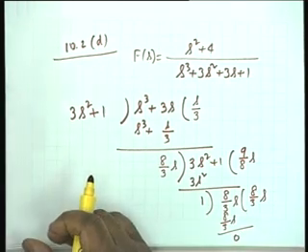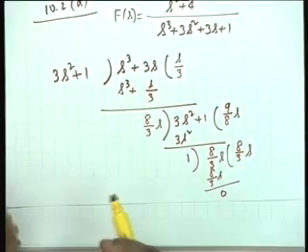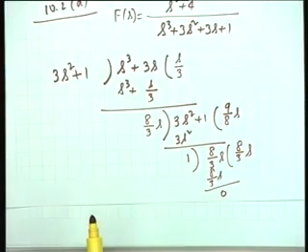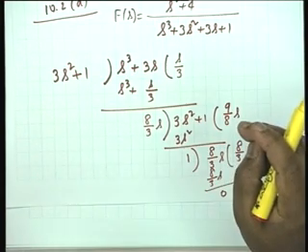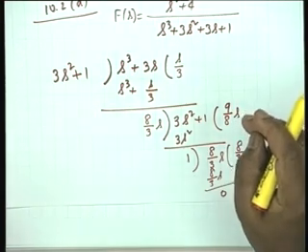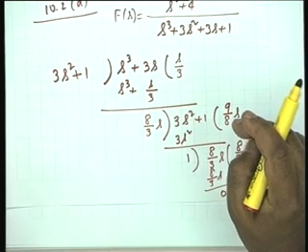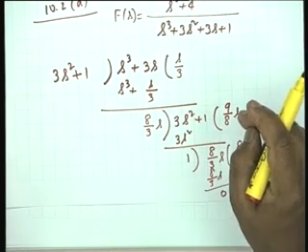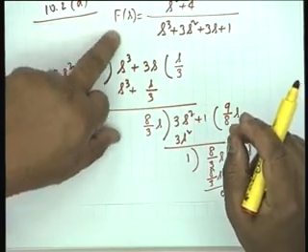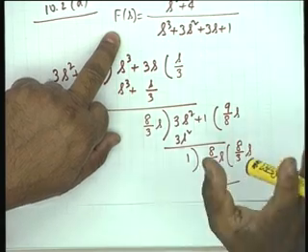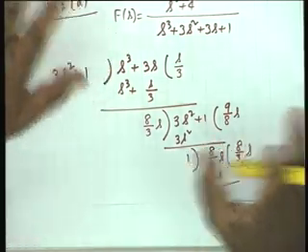The degree is 3 and I have got exactly 3 quotients, no premature termination, therefore no j omega axis poles and the denominator is indeed a Hurwitz polynomial, therefore the function has no poles in the right half plane. That part is okay. We don't have to check any residues.